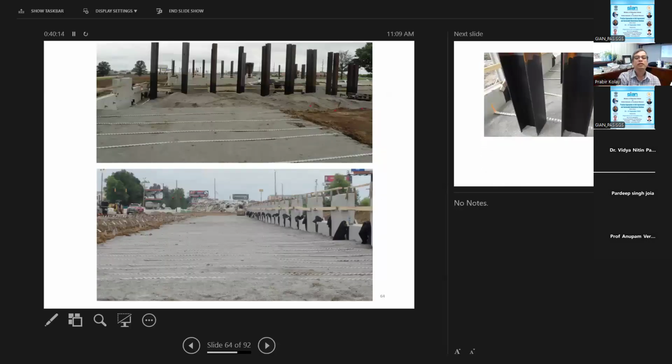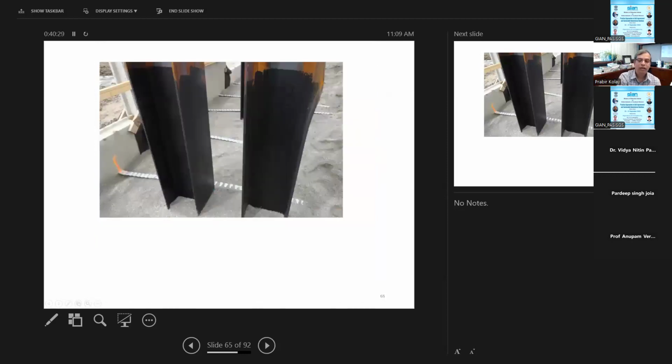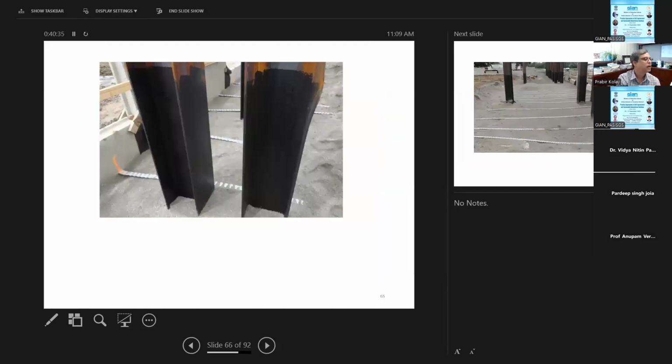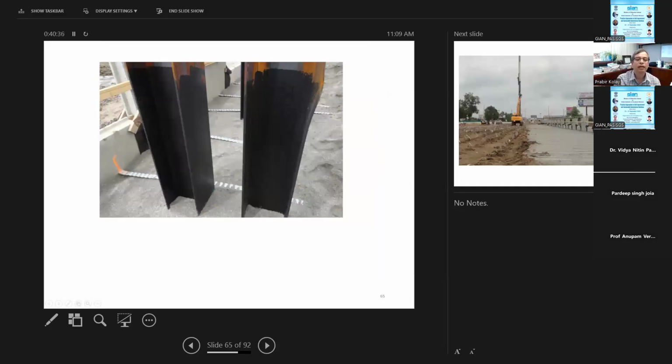And then put another layer like that. So this is again over here in Southern Illinois. I took some of the pictures of how it looks like. This is a metal strip, and also there is a concrete facing wall over here. So the concrete facing wall, how it looks like. You can see here there is a connector, just like this. There's a groove here. The metal strip can go inside and then put a nut and bolt there. So you can see the horizontal spacing over here.